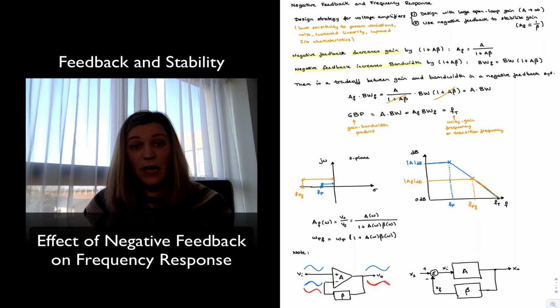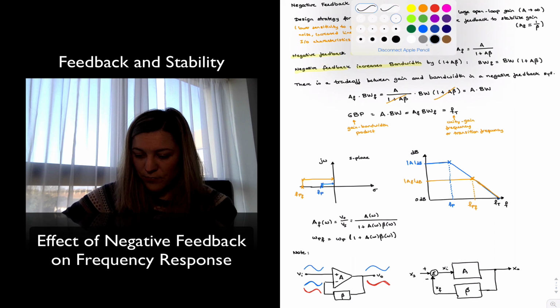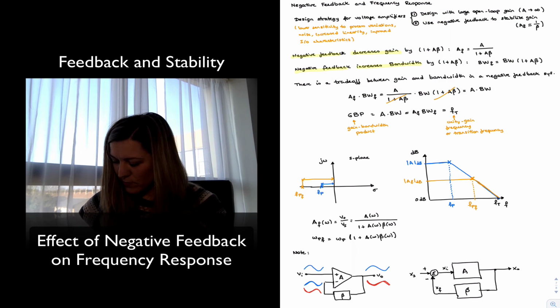Now, if I have a phase shift of my original source signal throughout the system of 180 degrees, that's equivalent to multiplying my signal times -1. It's basically taking the inversion of my signal. And so a 180 degrees phase shift is equivalent to multiplication by a factor of -1.